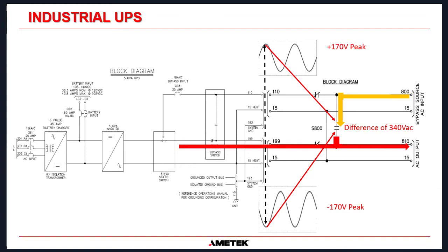I can't remember what the RMS value for that is. I'm sure somebody clever out there can work it out. It's going to be around about 240 or 250 volts. I can't remember, but there's going to be a huge voltage difference. And the only thing that's going to dictate where the current flows there is the resistance of the cables, the contacts, and everything else. So if you move the bypass switch when you have an out of phase supply, that is going to cause, in most cases, the bypass to feed current back into the inverter bridge.